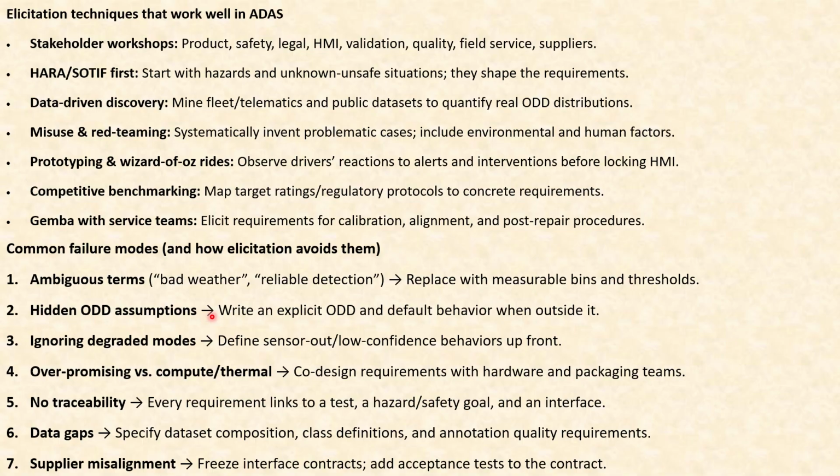Hidden ODD assumptions: write an explicit ODD and the default behavior when outside it. All right, the ODD must be explicitly written in as much detail as possible. All right, next is ignoring degraded modes: define sensor-out and low-confidence behaviors upfront.